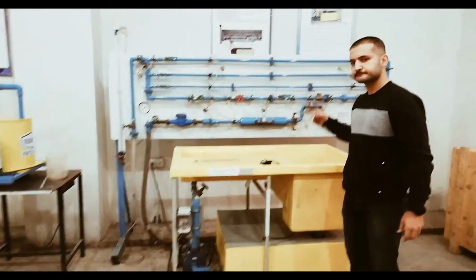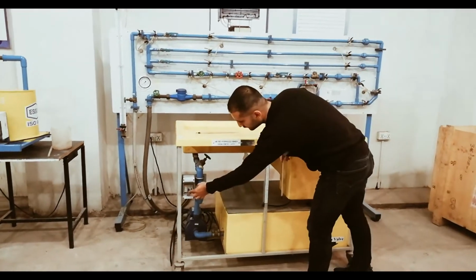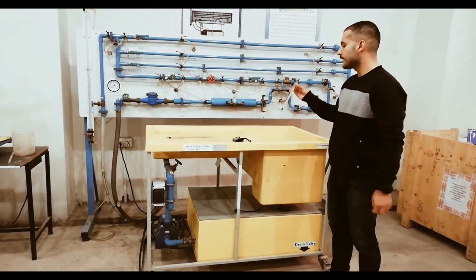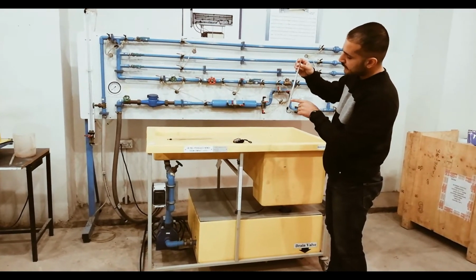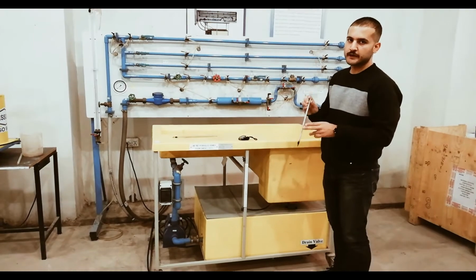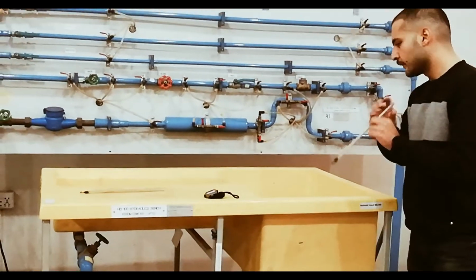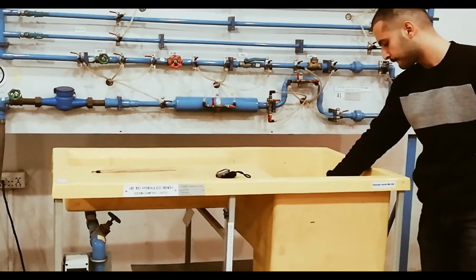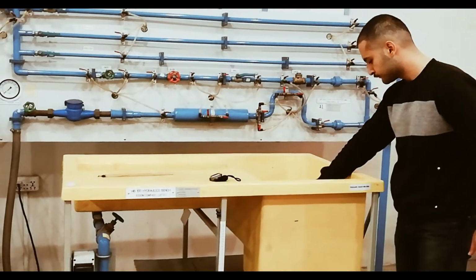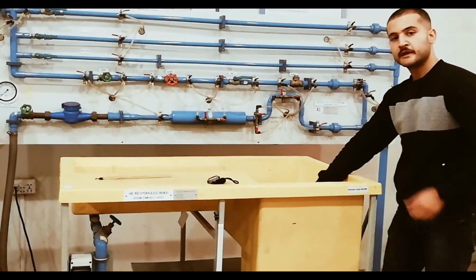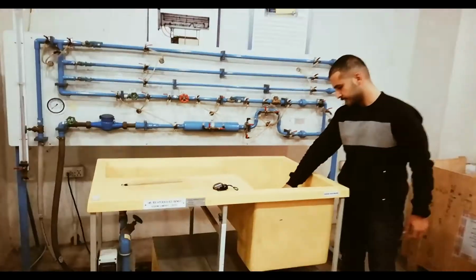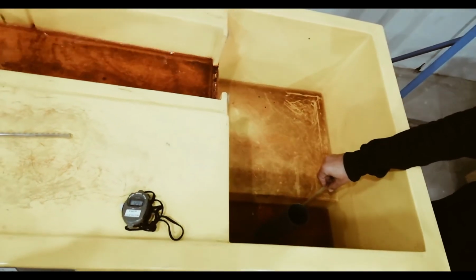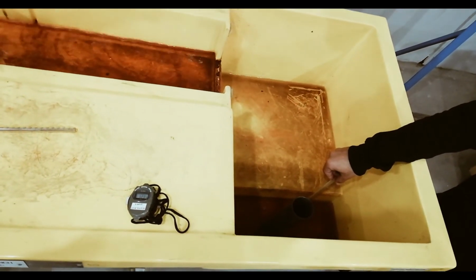Now further, for the Pitot tube, I am fitting it to my hydraulic bench. For the measurement, I am going to put it in the flow and measure the head, and from the head we are going to find the velocity at the Pitot tube. So I am closing the drain hole and putting the Pitot tube in. Let me show how it is happening. That's how I have placed the Pitot tube in the flow while it is gaining its head.